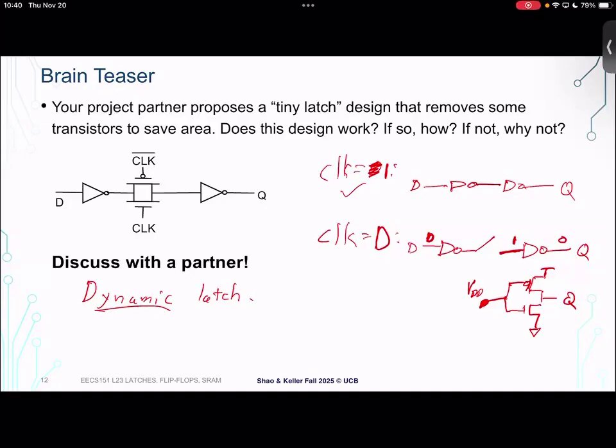Yeah. So this node, even when undriven, there's two paths for the leakage, right? One is it can leak through the gates of the following inverter. We haven't talked about all these details of how leakage works in this class too much, but there is the possibility of leakage through the gate of a transistor.